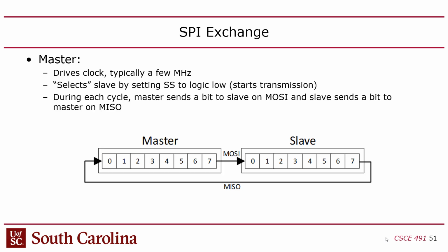So every time you initiate an SPI communication, you're taking a word, in which case, in SPI, by the way, a word is considered 8 bits. This is a little confusing because remember, ESP32 has a 32-bit word, but SPI communication is done in units of 8 bits, right? So you take an 8-bit word and you send it from one entity to the other, and from the other entity back. So you do an exchange, right? The master sends 8 bits, the slave sends back 8 bits, right?